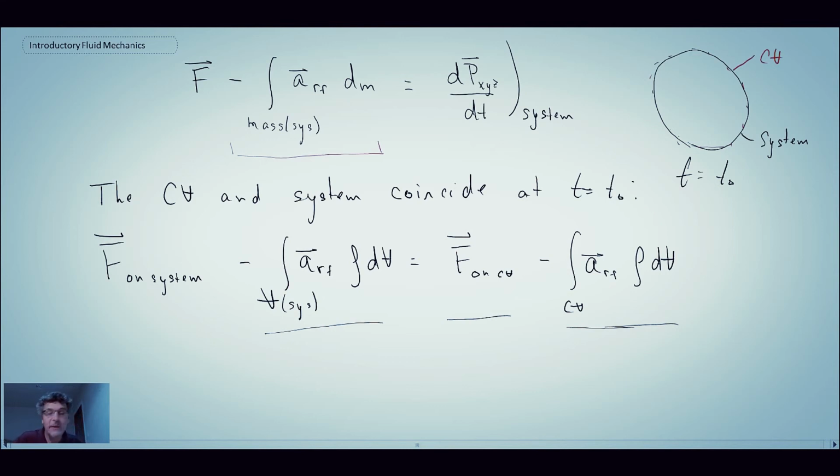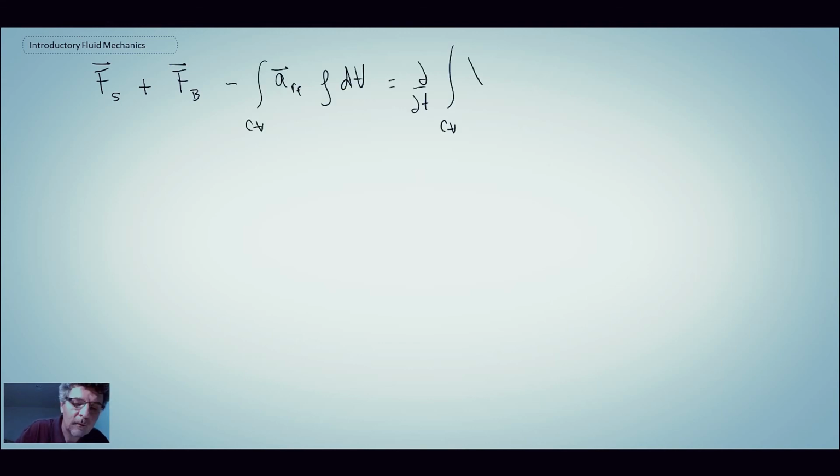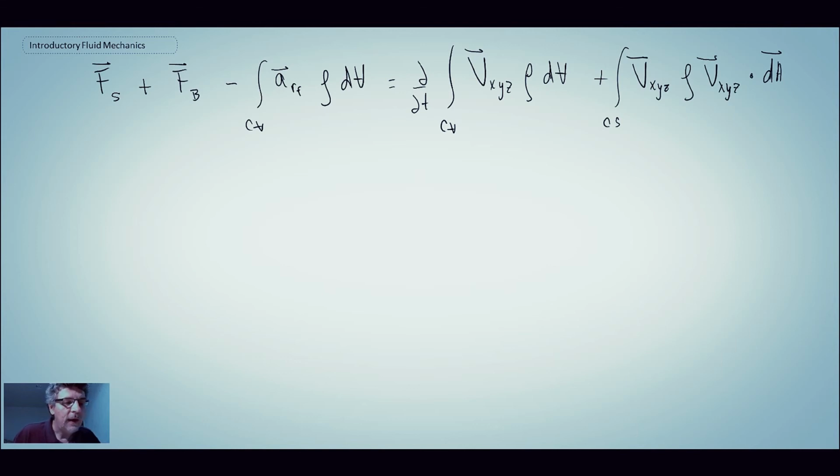And so with that, that will enable us to rewrite the linear momentum equation, but now it is being expressed for the case of an accelerating rectilinear, so it's just going in translation, control volume. Okay, so that is the equation that we end up with.